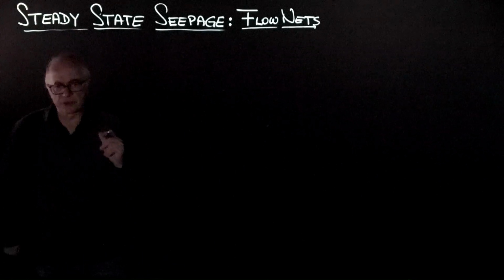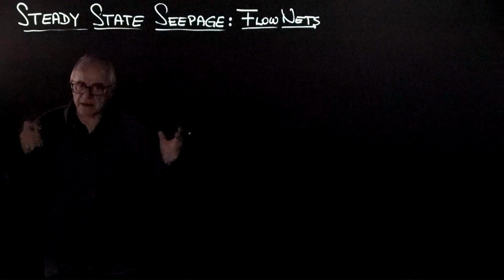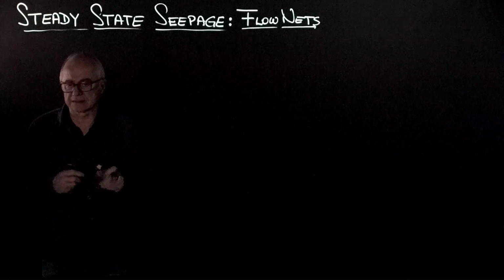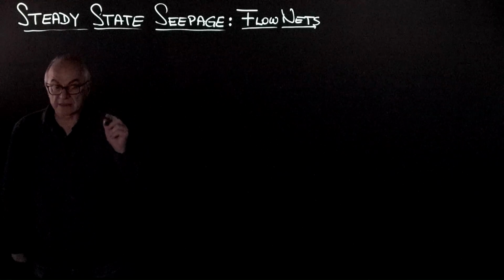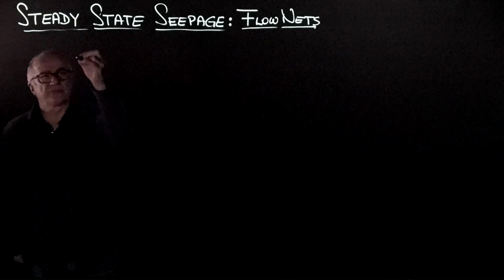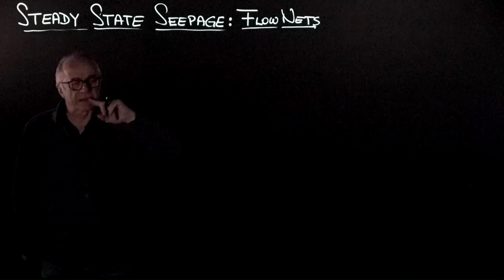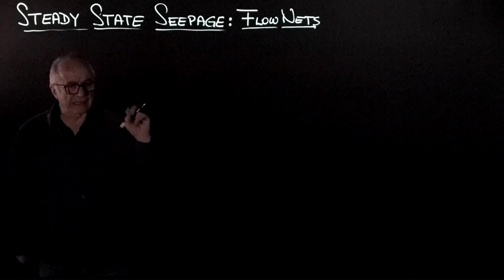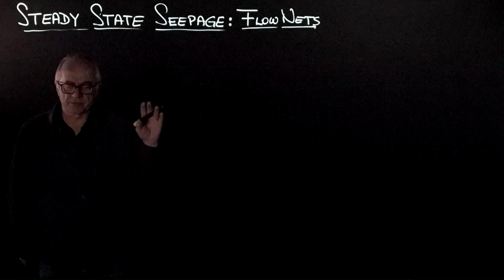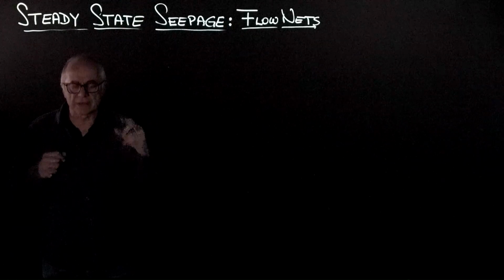In one of our previous meetings, we derived the structure of the key equations that we need to understand steady-state seepage. We started by recognizing that all motion is energy-driven. Therefore, the total energy was equal to the kinetic plus the potential plus the pressure. In most cases, the kinetic energy will be a very small component, so the total energy will be the elevation-related potential energy plus the pressure in the fluid.